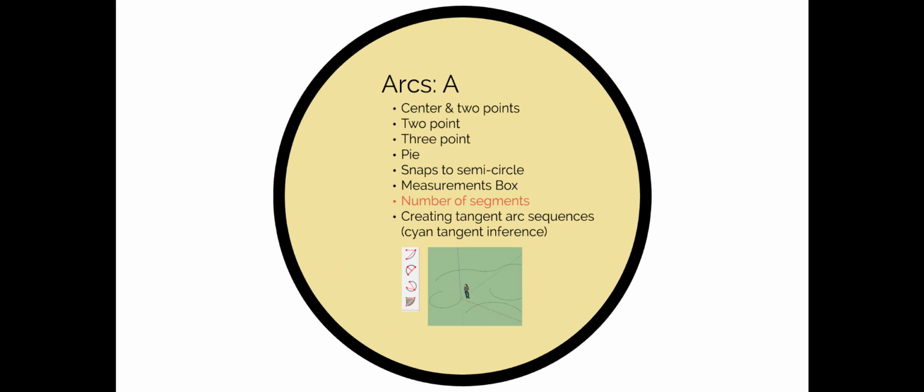Arcs, there's a number of options using the arc tool now, some that create a pie and actually close it in. Other ones like 3-point just give you a beginning and end and a bulge distance, or you can put a radius in itself. So again, it gives you a really quick way to do kind of free form, curvilinear, arc and tangent type forms.